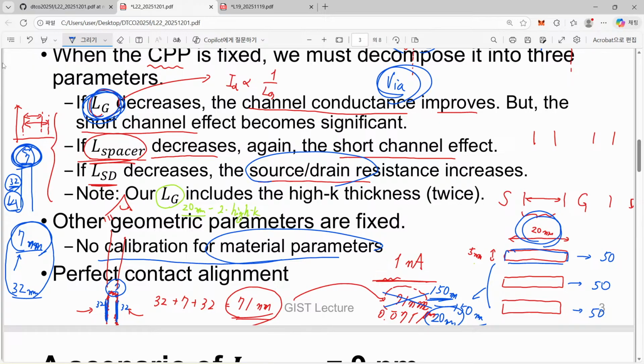However, in the case of a nanosheet, the thickness of the channel layer is more or less given as 4 point something or 5 nanometer. So it is given. The designer can just change the drawn width of our transistor, so it properly corresponds to the change of our transistor. Only the exaggeration comes from this additional factor of 3.